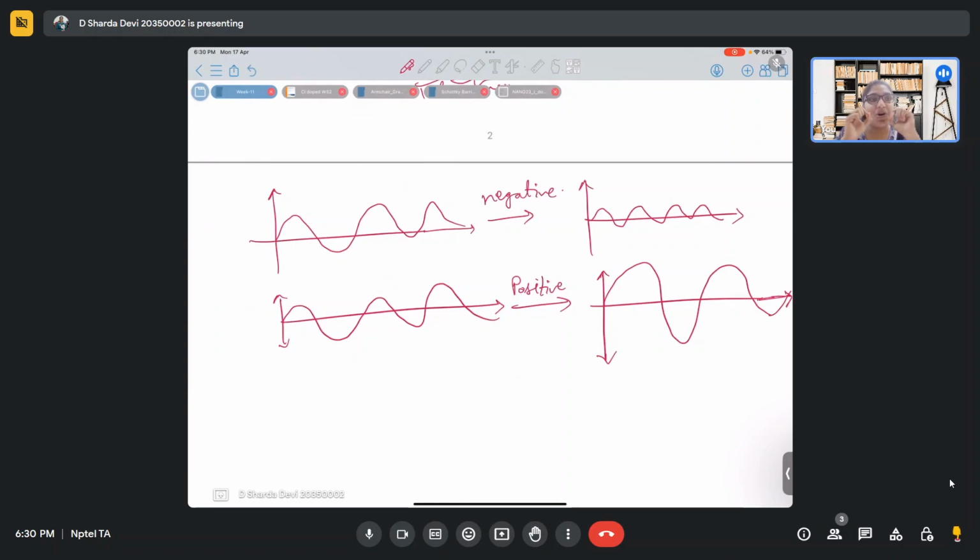That small trigger is sometimes the noise that we get, the thermal noise. That basic thermal noise gets amplified multiple times in positive feedback, and finally we get that resonant state where it stabilizes itself and we get that beautiful sine wave. That's nice, but can we always count on this thermal noise?